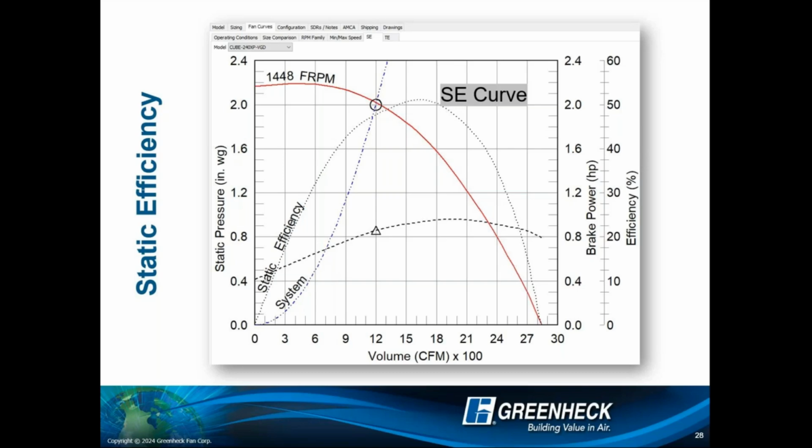This is telling you where this fan's operation is most efficient, right? And okay, I'm going to go back on the screen. Right here is the peak of this curve. Boom. Right here is the peak of the curve. That is, if I was operating in line with that, that would be operating this fan at its peak efficiency, right?